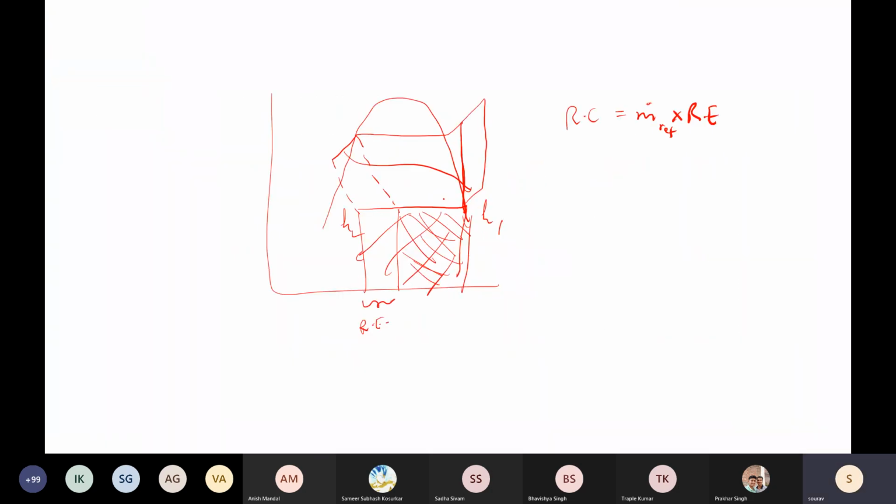What the first statement says is, if you have a large superheat horn, this is the superheat horn for the standard cycle. If you use an LSHX, you now send the superheated vapor into the compressor, so your superheat horn becomes even larger compared to the previous case. So statement A is wrong.